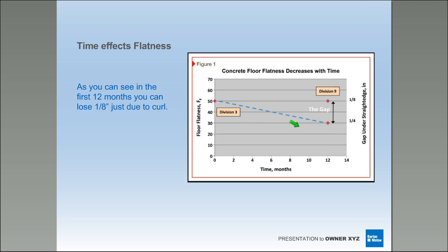So keep that in mind when scheduling when you want to polish and when you can get in there and when it's most advantageous. To me, the sooner I can get in there, the better, at least with my diamond cuts. If they can let me in there in 14 days, give me it in 14 days. I want to get in there, get my diamonds done, protect the floor, and I'll come back and refine. But at least I'm not cutting into anything that's curled too much where I'm going to start seeing all these rock pockets and everything else. So just always keep that in mind.